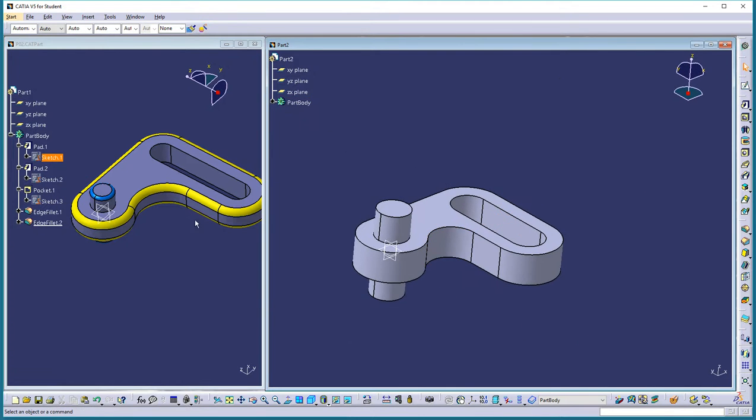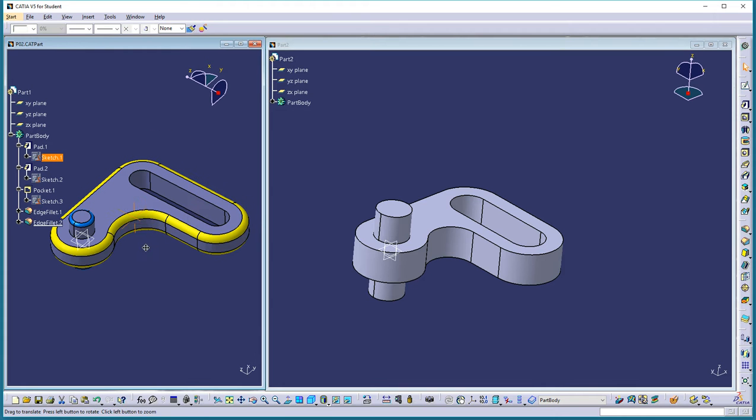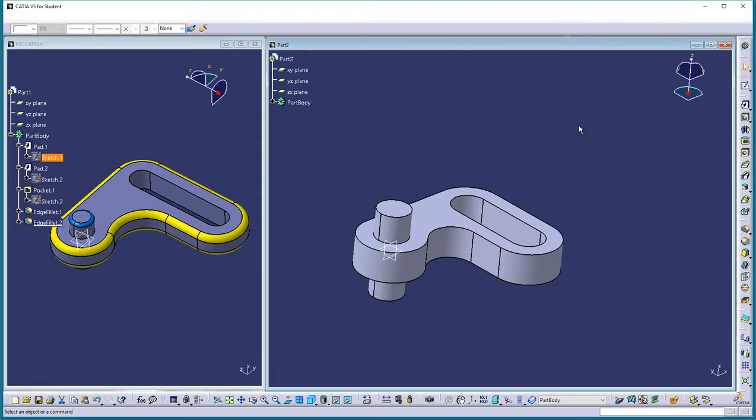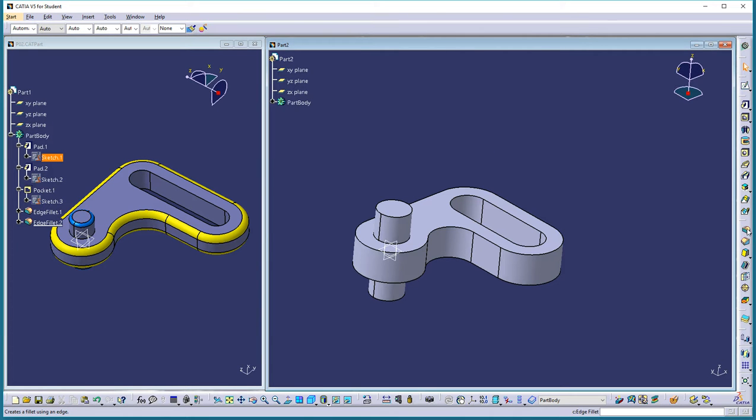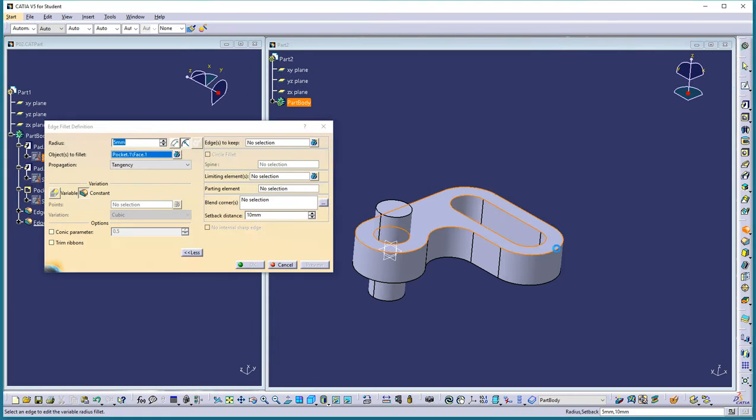Okay, the last thing we need to do is put a couple of fillets on. Of course, the yellows are 10 and the blues are 5. So let's put a fillet on of this edge. Oops, I accidentally got the face. So I'm going to select it again to turn it off and be a little more careful this time, picking just that edge and just this edge. And those are going to be 10.